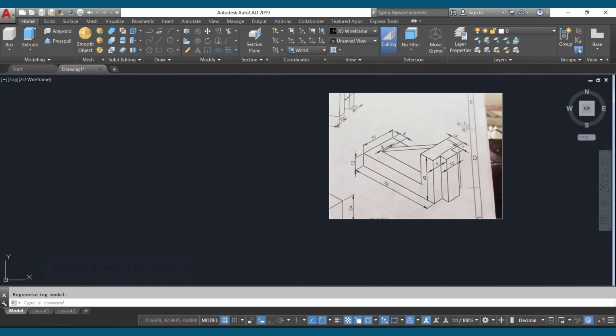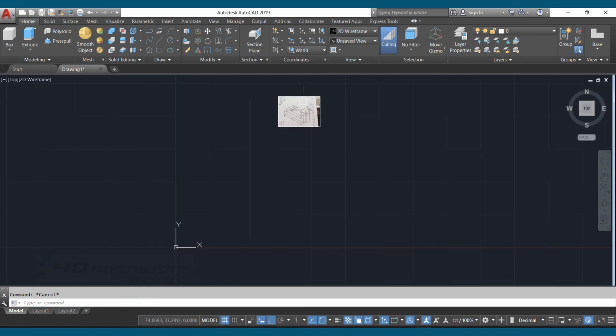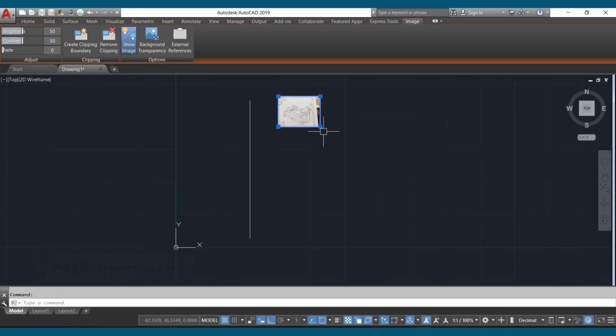Next we need to start with this front view side. So we have this height here 42. And this length is 76. So we are going to start with this figure. I'm going to consider this side as a front view. So take the line command, put ortho mode on. Here the length is given 42. The image is looking very small, so we'll scale the image first.